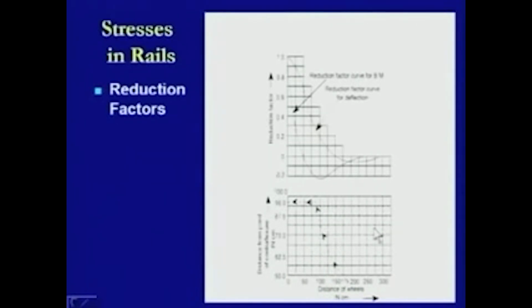Now, we have to find out this distance from the point of contraflexure on the basis of the value of x, as we have seen previously while computing the bending stresses or the bending moment. As soon as we have computed the value of that x, we can find the distance from the point of contraflexure in centimeters.